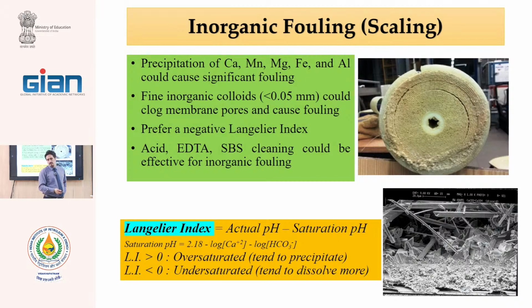In the dairy industry, we wash the membranes every day with hot water, and every week with cleaning agents such as surfactants, acids, and bases. In RO, we usually wash the membranes every month. When I say wash, we use only water, or water with air bubbles, no chemicals.